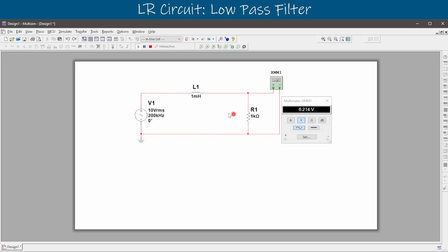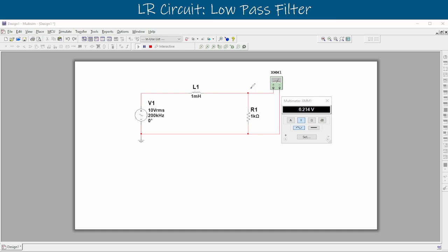And if we were to flip these two components here, we would see the opposite. Right, we would have a high-pass filter instead of a low-pass filter like this one. And remember that these are filters, right? So we are going to use these to filter out signals. And sometimes that's an audio signal, so we can place another circuit here that leads out to a speaker of some sort. And if we don't want the higher frequencies to come through, like a high-pitched squeal, we can put this circuit right before that speaker.